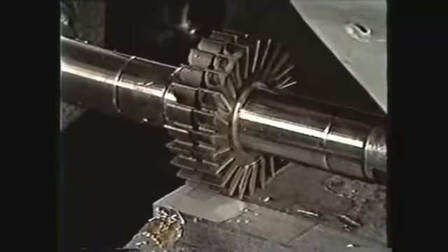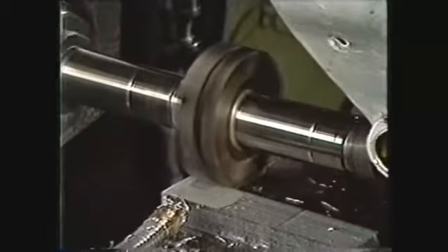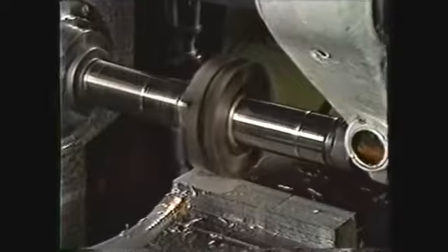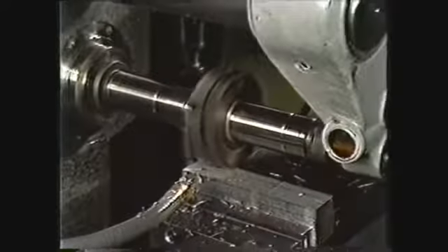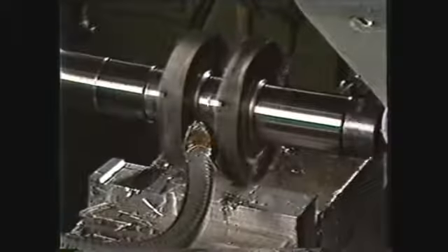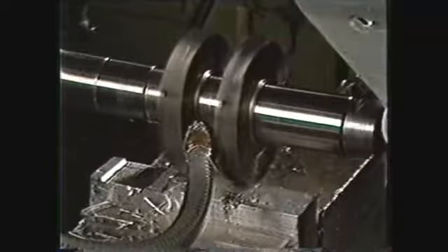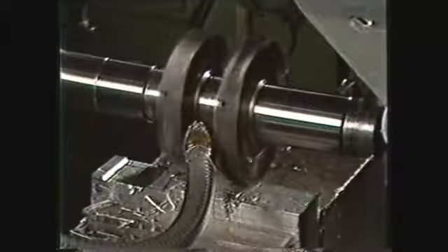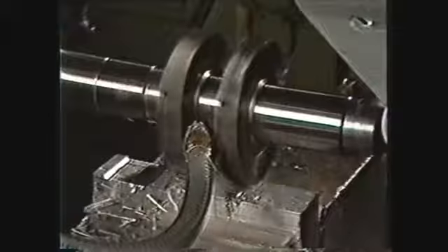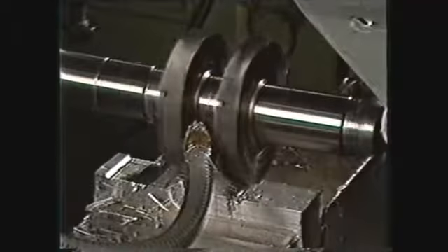When cutting slots of over 1 inch wide, 2 or more side milling cutters may be mounted on an arbor together. If 2 slots are to be machined with a ridge left between the slots, a spacer of the exact dimension of the ridge can be placed between 2 cutters to machine the slots simultaneously.